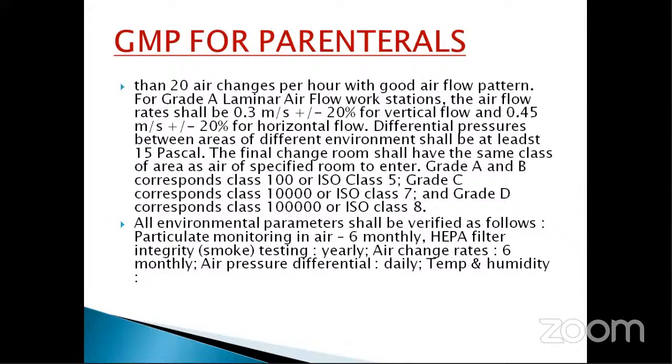So if it is an A grade room, the aseptic room, where the final preparations of injectables or sterile products are done, its pressure will be maximum. Then the next 15 Pascal lower pressure will be in the B grade surrounding rooms. Whenever you enter from B to A, you may enter, but the air of the B will not enter because A is the higher pressure area. The doors will be opening on which side? The door will open on the higher pressure side.